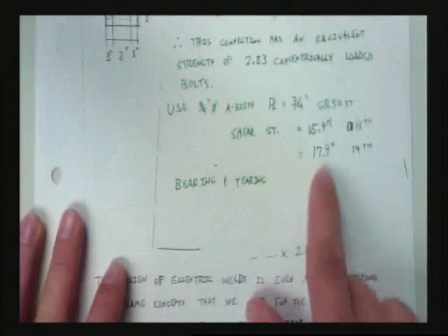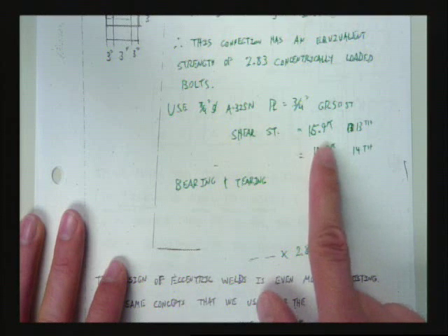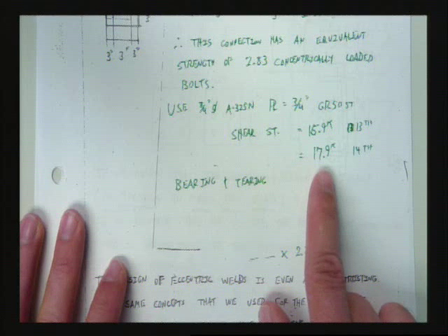And I have 2 strengths down here. Why do I have 2 strengths? Different manuals. The 13th edition reports 15.9, and mysteriously, all the bolts have gotten stronger. Well, they've changed the safety factors on bolts.